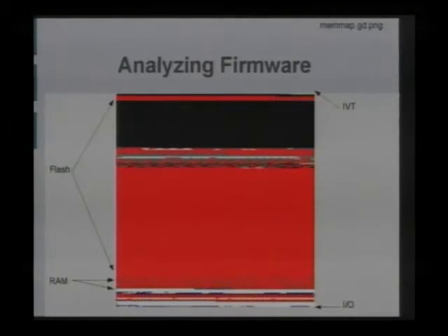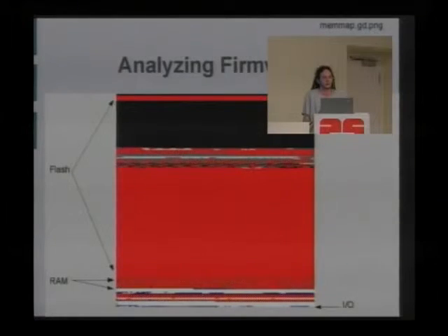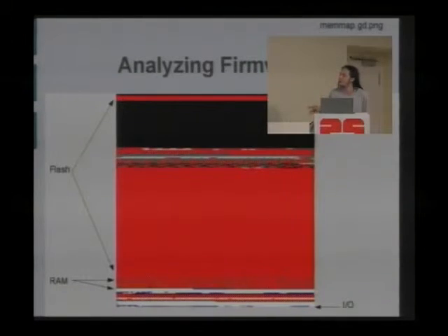Firmware analysis tools, or I suppose it's not firmware in the 32-bit range. So on a PC, you have IDA Pro, and IDA Pro uses lots of very sophisticated algorithms to search in anything approaching a reasonable amount of time. On this chip, all of memory is 64 kilobytes. 32,000 instructions is the absolute maximum. And so you don't need these advanced, fast algorithms that make IDA Pro possible.